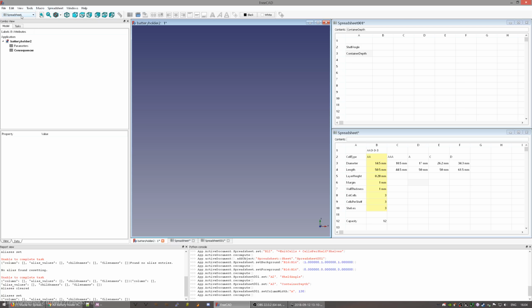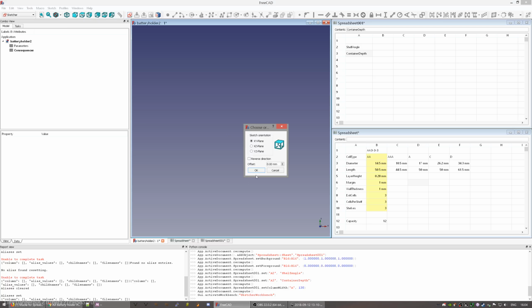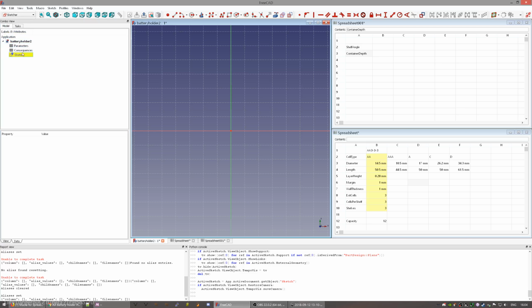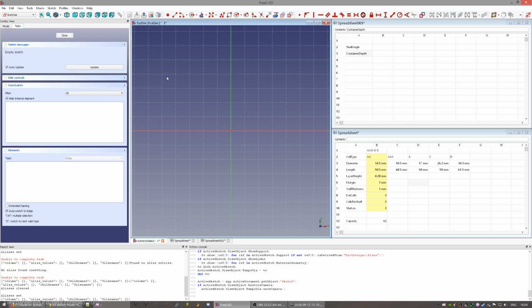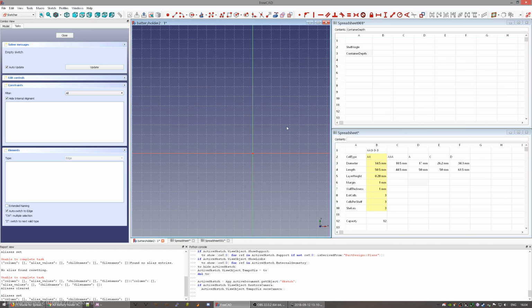So, time to actually start designing things. I am going to use the Sketcher, and the Sketcher is the same tool that you use to design sketches inside of part design, but in this case I am making some standalone sketches. As you can see here, it's not inside any part or body, because I want to use them to draw some of the properties.